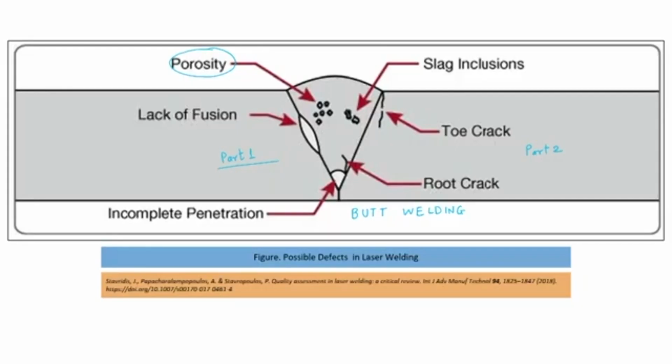Sometimes they get entrapped inside the work material and slowly get released. Due to the release of these entrapped vapors, there are chances of having pores inside the weld material, which is not desired.